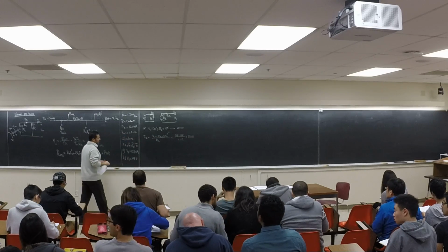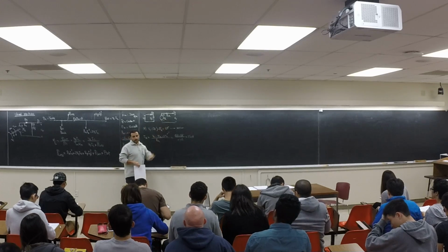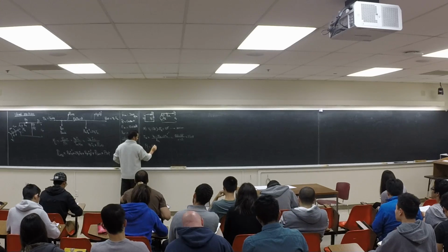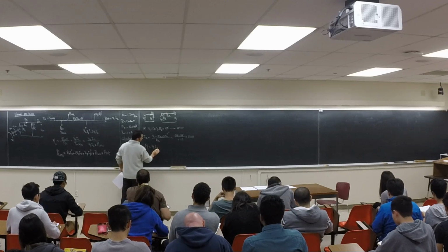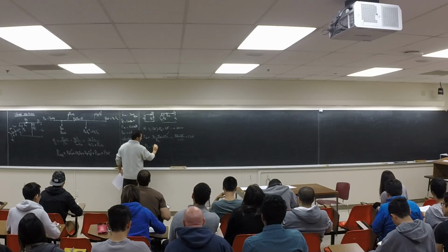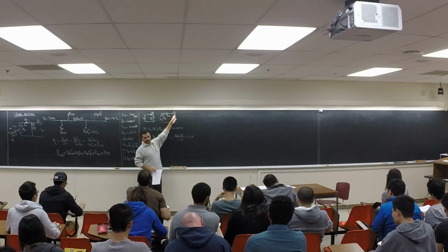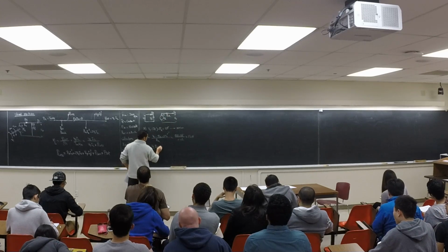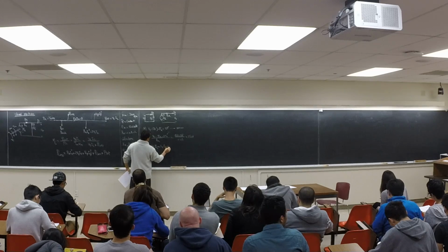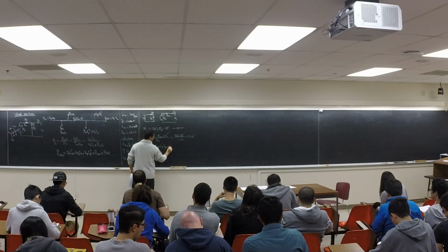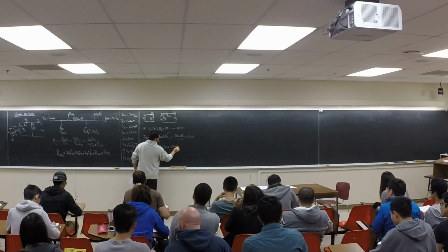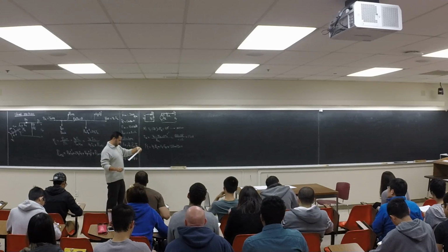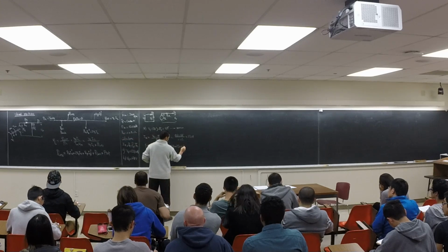It says calculate the PT, P terminal. In this case, it's the input power. How much is the PT? VT, IA. Usually we call it IL, but in this machine, IL and IA are the same, right? I'm saying usually they use IA. So VT times IA, how much was it? 128 times 150. If this one is correct, it is 19.2 kilowatts.